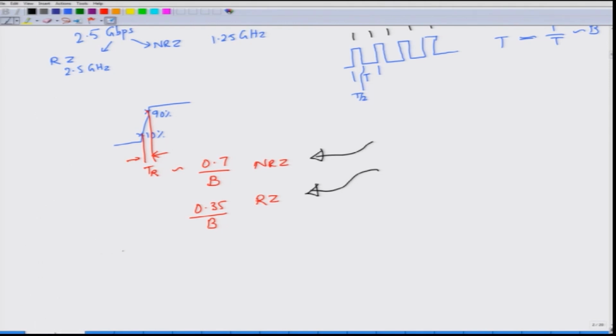So, let us see how we can look at this. Rise time in optical communication systems is given by three factors. So, there is the total rise time, let us write down, which we call the system rise time. This is given by tau t squared, which is the transmit rise time. This quantity is not very important in modern optical communication systems. About 10 to 15 years ago, this was important because your lasers were directly modulated. Today you use an external modulator as we discussed.